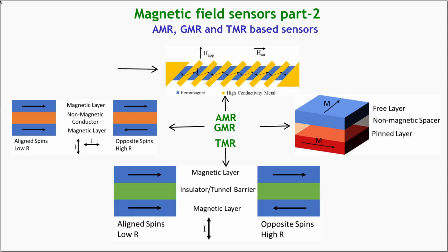Hello, welcome back. In the second part of the magnetic field sensors video, we'll discuss the AMR, GMR and TMR based sensors. We'll start our discussion with AMR based sensors, or the anisotropic magnetoresistor based sensors.